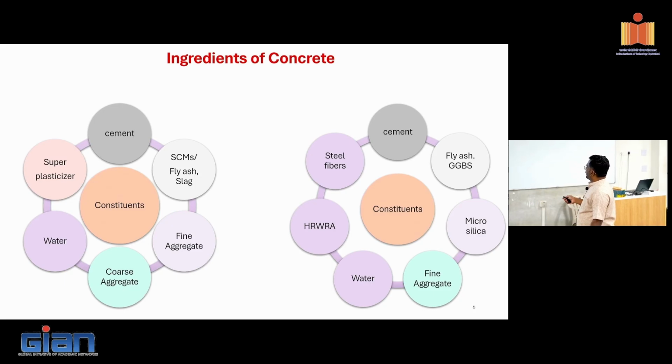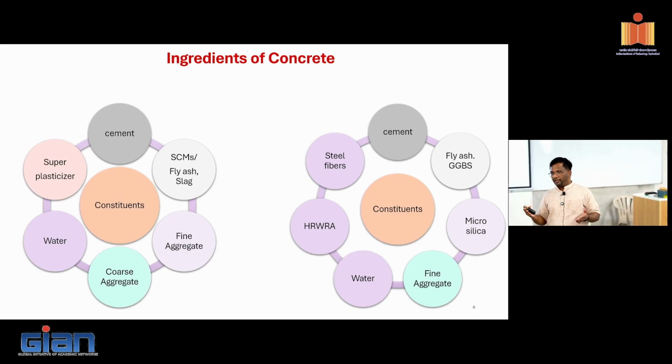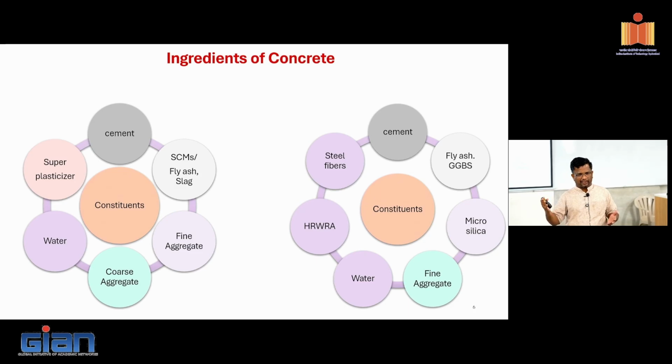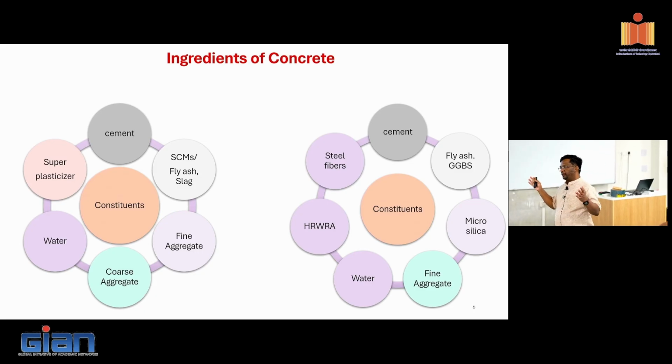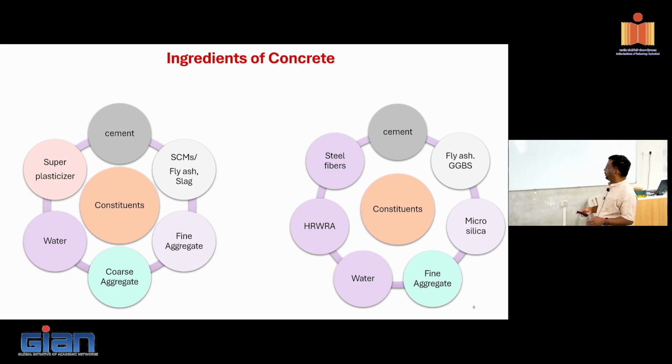So it is fly ash, GGBS, where does it come from? From blast furnace slag. GGBS is blast furnace slag. So, again in India our steel requirements are so humongous, right? In fact, roughly they say 1 ton of steel almost leads to about 0.8 tons of GGBS, slag, I should say. Slag again goes through multiple purification processes. We have a humongous amount, we don't know what to do with blast furnace slag also. So that's the reason we try to take advantage of these properties by putting them in concrete. That will help you in multiple things.